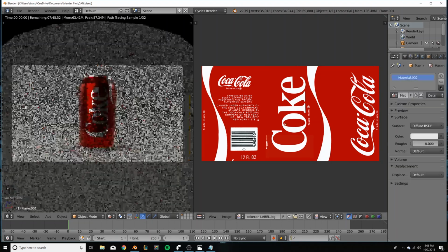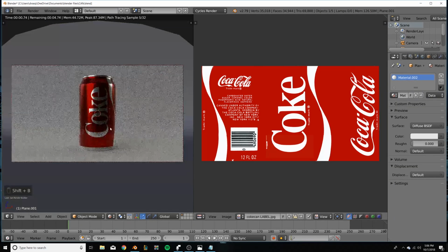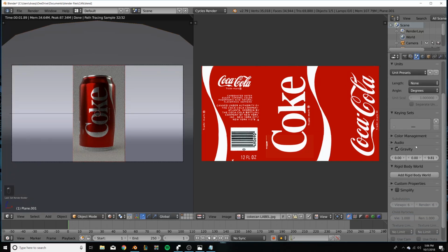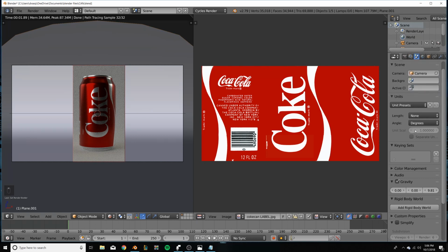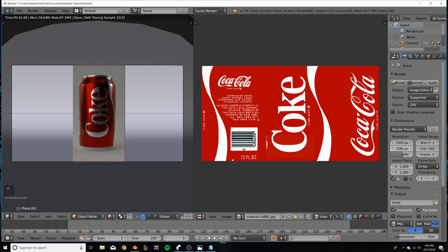For this background, just hit new and just create a diffuse material so we can see just the diffuse. Now go to scene settings. Or render settings and set your resolution to your max resolution.